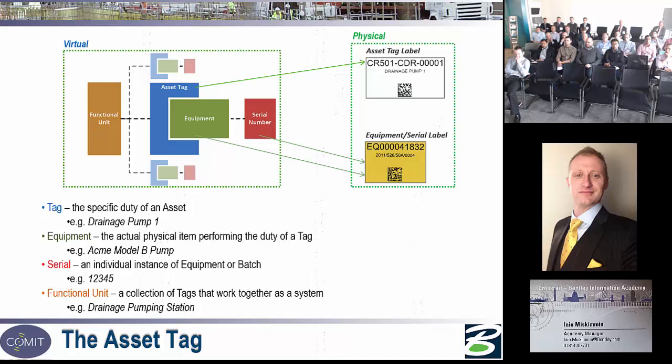You don't even have to label everything. That's just an example. Things like a concrete floor slab or a pile, you probably don't want to label. What you might want to do, however, is drop something like an RFID tag into a pile cap, because in 150 years or 50 years time when the building is demolished, repiling or finding out what the pile is actually capable of is very difficult. If you can identify that pile, then you can reuse it.